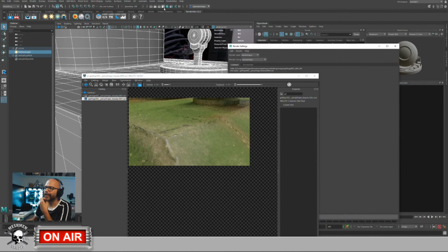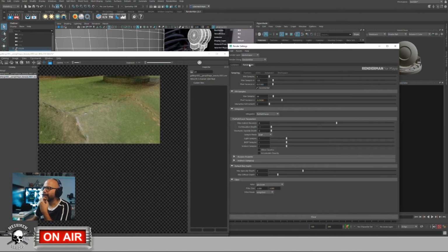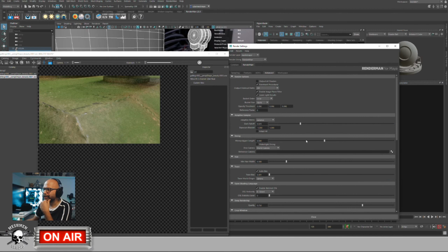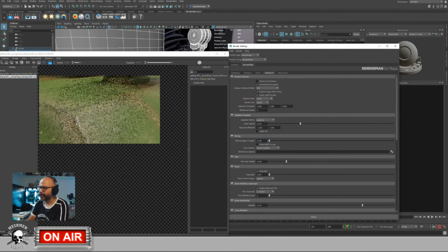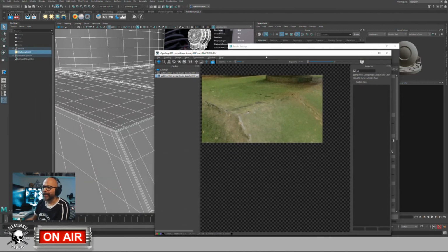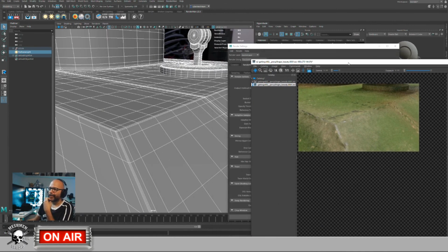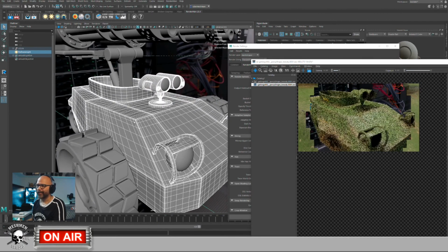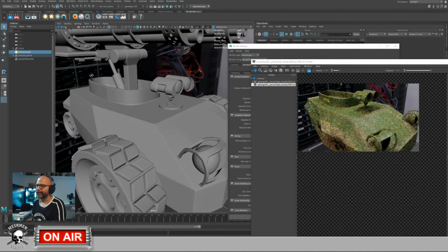Okay, so I wanted to test here my Renderman micro polygon length. Doesn't look like it's updating on the fly, so yeah, it's probably one of these settings that you need to refresh. But anyway, micro polygon length is essentially, if you lower it, it's gonna dice the geometry further, so you can get more out of your displacement. So that's essentially taking out from that. Okay.